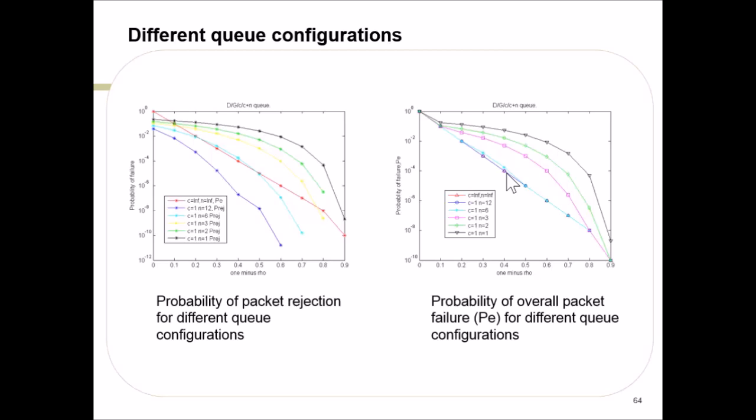But the advantage is, because you are updating these, let's say 100 check nodes, you're updating all these bits, let's say you have 1,000 or 2,000 bits, all those 2,000 bits which are connected to this check node. Then when you're updating the next 200 check nodes, you're looking at the already updated bit nodes. So you're getting the latest information. Better estimates, basically. Yeah, essentially you can think of it as an estimation improvement. So it's decoding faster because you're using the new data. New data, exactly, earlier.